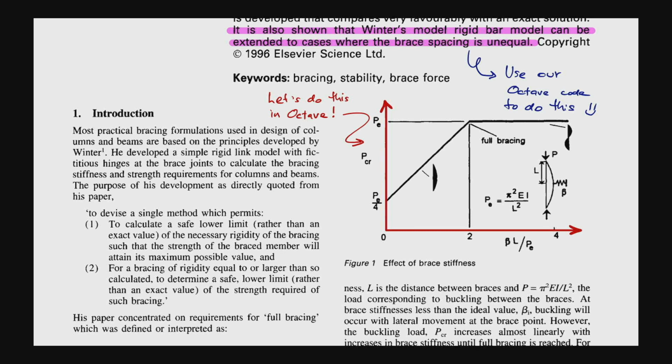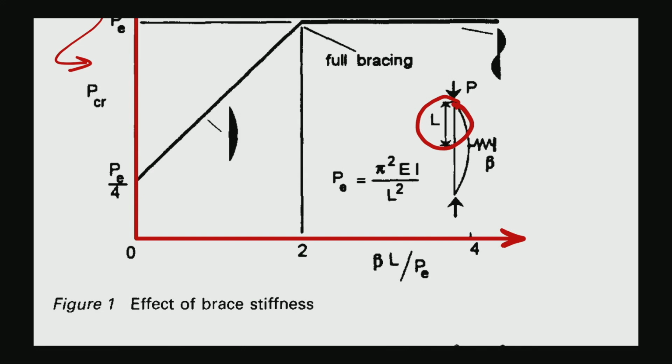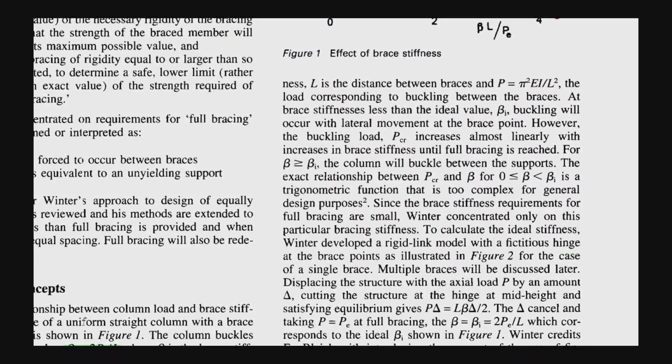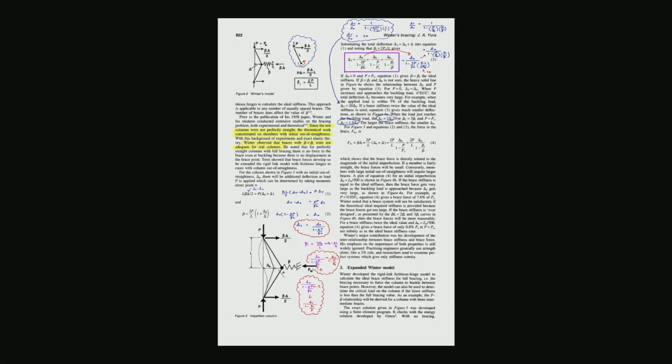Once you achieve that full brace stiffness, then you get this buckling shape. You form one whole sine curve buckling instead of half sine curve. And then the L is given by this length, the length where you need to develop the full brace capacity. You want to develop the buckling over this and over this, just these two areas. Now we come to here. The L is already defined. You know the P, which is the buckling load, critical P. This is just the explanation I have gone through so far, so we can move to the next page.